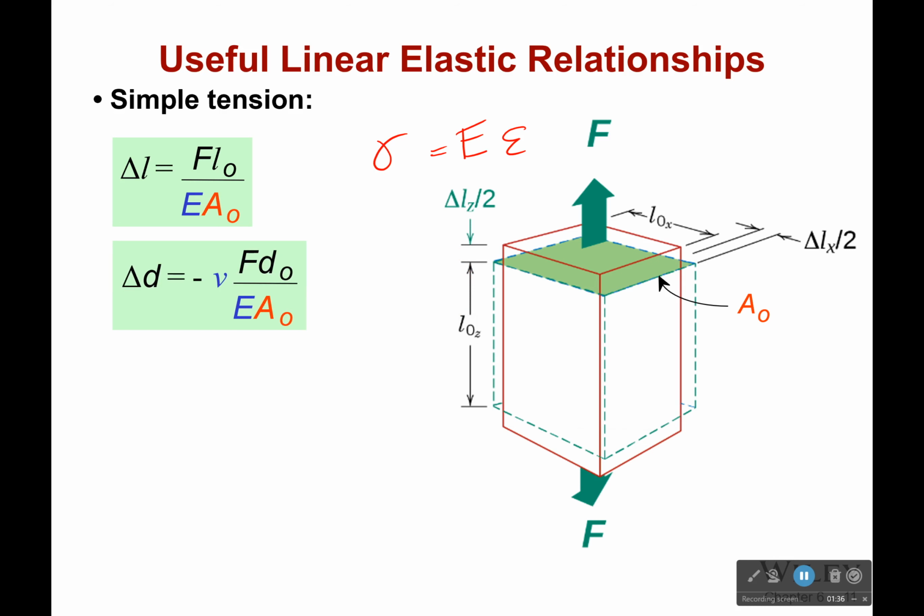So I've got two equations here, and one is saying, what's my change in length? Well, that's going to be equal to this guy. What is that? It's what's usually called the FLEA equation, because it's saying, I don't really care necessarily about what my strain is, I want to figure out what the change in length is. Sometimes that's more important, and so this just goes straight to the point. Now where does it come from? Well, you know that force over area is stress.